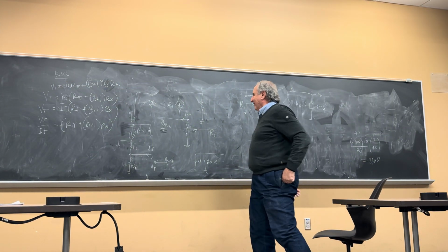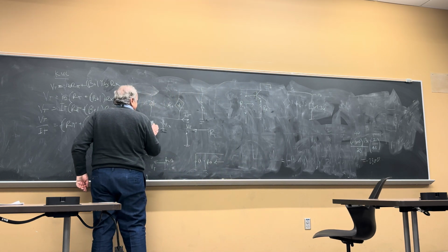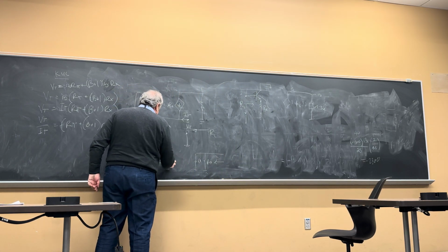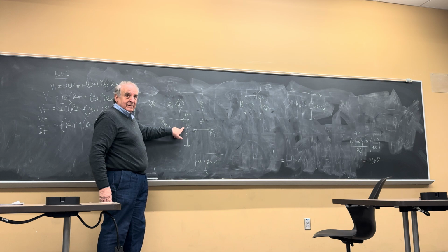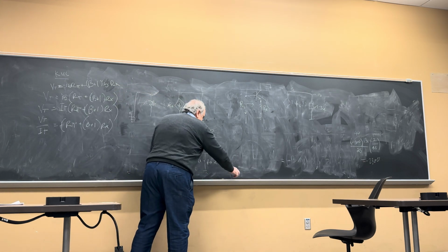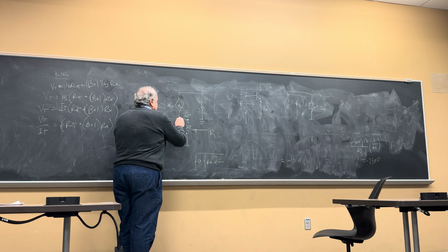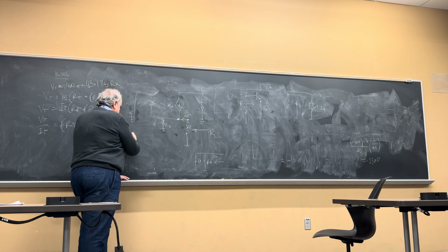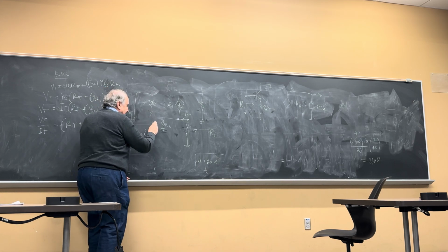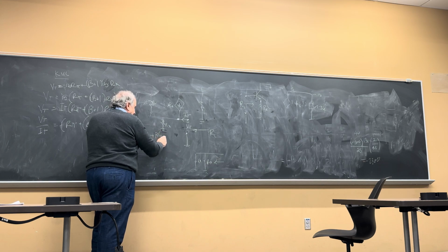Of course. Let's do the pi model. This is the pi model, right up here, and I'm looking here. Let's do KCL right here. This is IB. I sub T coming in plus I sub B coming in plus beta IB coming in, this one, minus Vt over Rx equals 0.